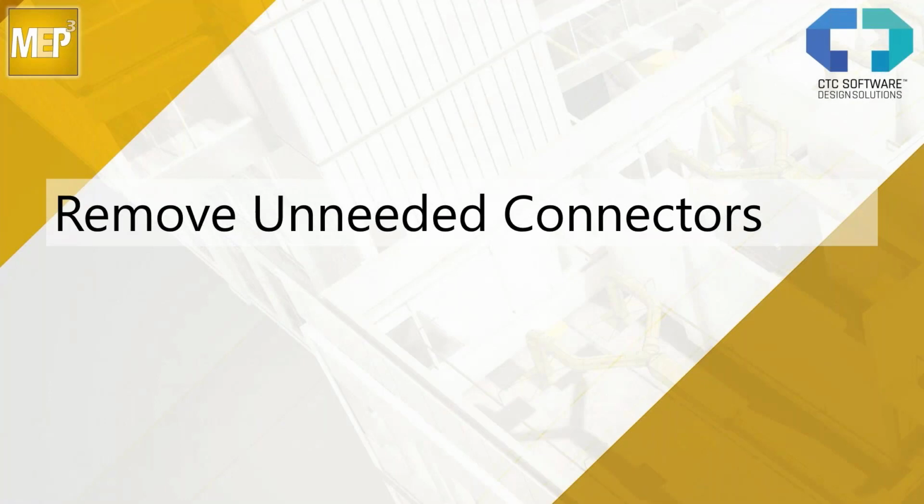We only need specific ones. We want air supply, air return. We want the 2 DX connectors. Maybe I want to keep the chilled water supply and return lines if I wanted to have that secondary feature. But pretty much everything else is self-contained in this unit. I do want to keep the condensate, but everything else I pretty much want to get rid of.